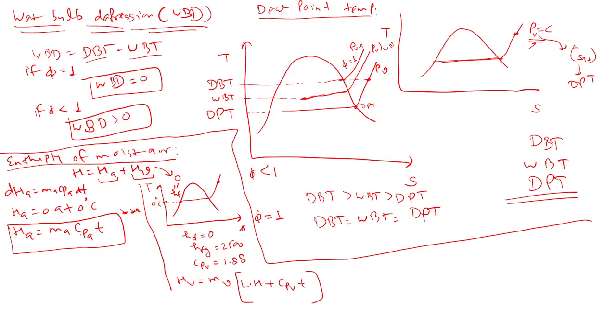Cp we know for air 1.005, mass you will be calculating. So that I will tell again. MV into latent heat, now you know 2500 we have written, 2500 plus 1.88 into T. So now this is HV.